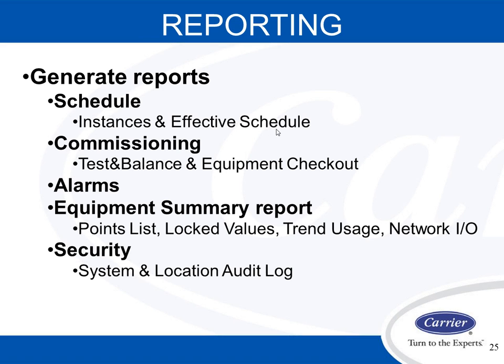Reporting. You can generate reports, and inside the reporting you can do reports on schedules, such as just the instances and the effective schedules. Commissioning would be another report, so you can see test and balance, or there's a section there for equipment checkout, so if there's any notes that's left. You can also do reports on alarms, along with the points list, the lock values, trend usage, and the network I/O.